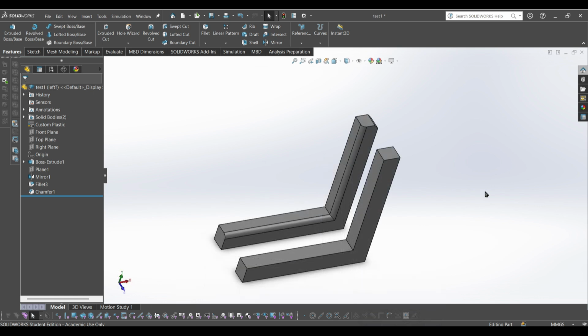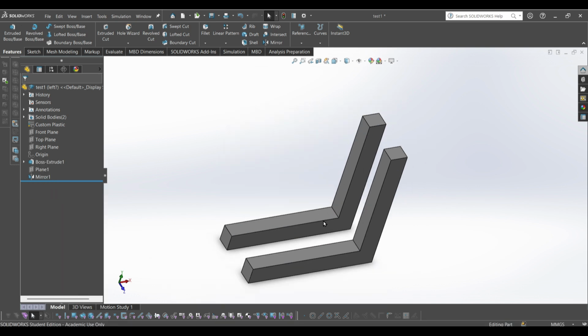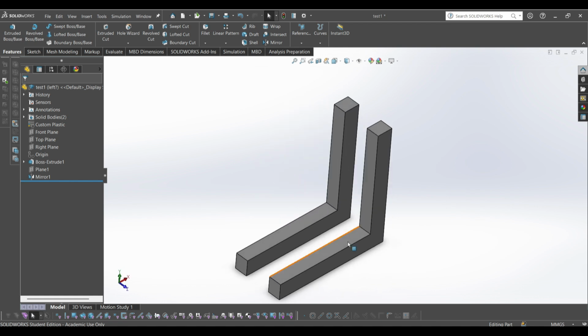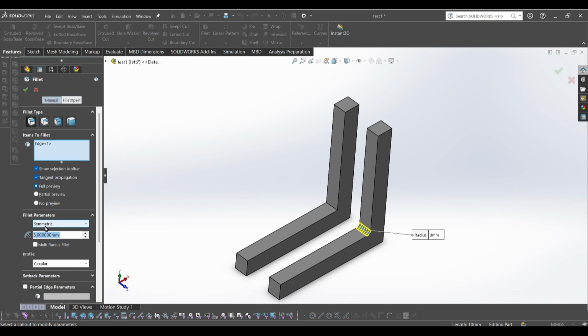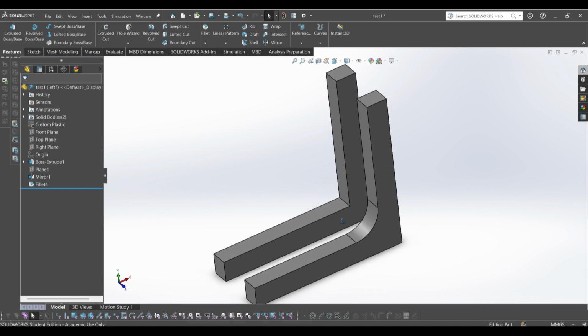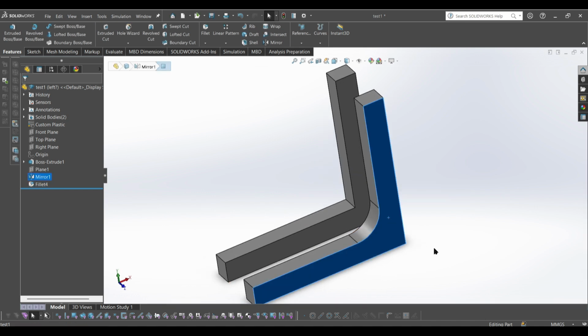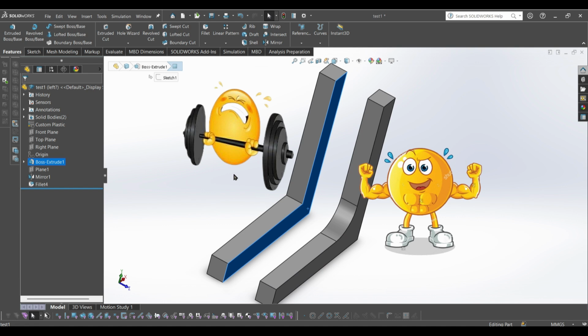So the Fillet and Chamfer tools are really, really important for understanding and knowing in FTC because they can drastically change how strong your actual part that you 3D print is. So for example, I'm going to delete these. If you look at these two pieces, they're both the exact same. But if I added a fillet or chamfer here, say I made it 15, this part, this L piece with the fillet is going to be much stronger than the one without a fillet.